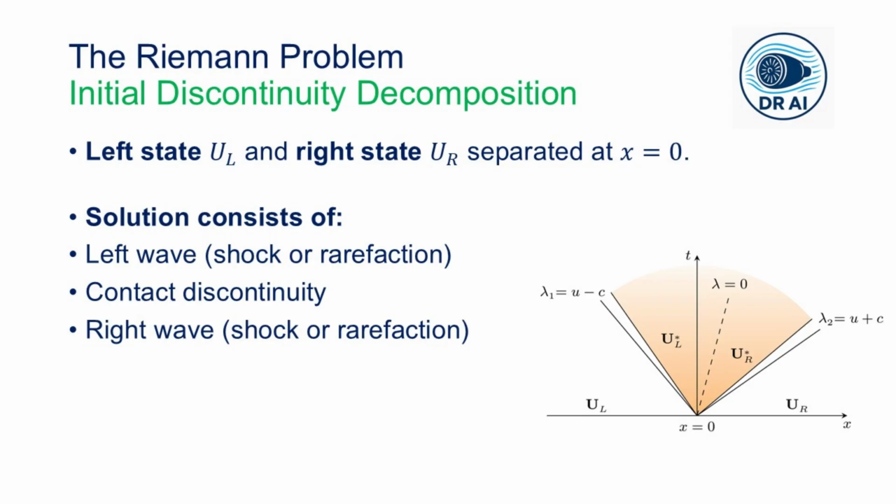Now consider a 1D nozzle with an inlet Mach number of 2, which represents a supersonic condition, and an exit Mach number of 2.5, which is also a supersonic condition. In the supersonic region, all lambda would be greater than 0, which means that downstream perturbations cannot influence the upstream. That is why a supersonic nozzle is governed solely by its geometry.